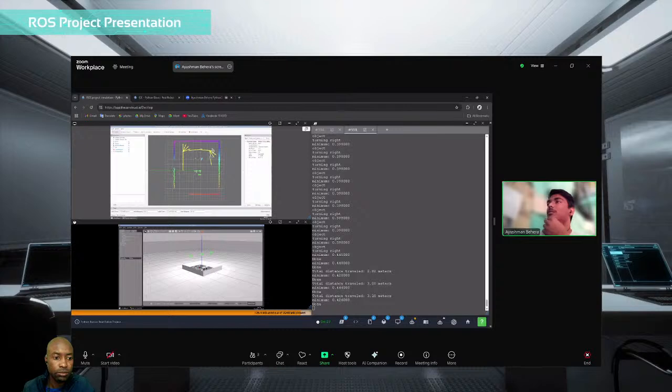Every time an obstacle is detected, it will take a step back, moving backwards a little bit. Then it will scan left and right, depending upon which direction it should move. Like here, it saw that this side was blocked, but this was clear. So it assumed the right side was clear and will turn right. In case this was a wall, as long as the wall was not out of its bounds, it would turn, and then continue its path.